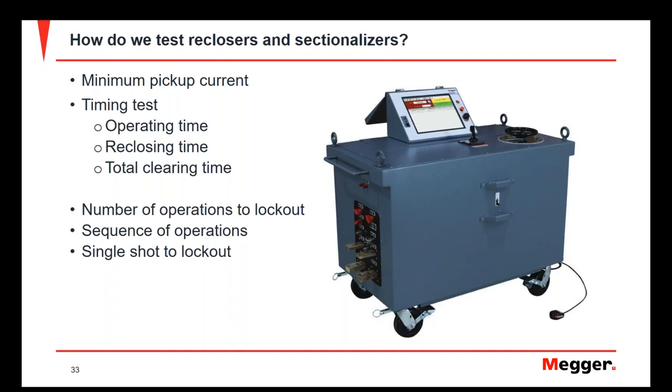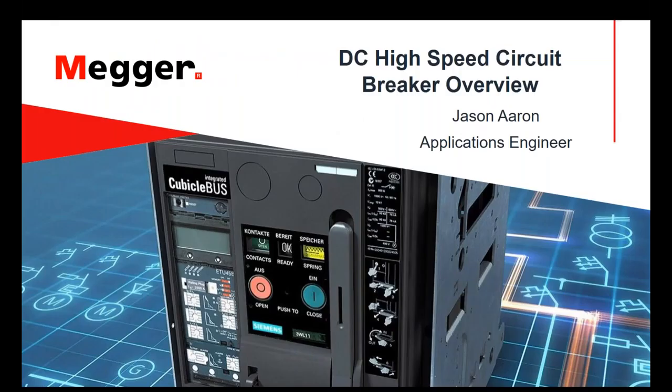And even though all of these processes can sound kind of complicated, the testing of these reclosers can be done safely and easily using a test set similar to the one we see here, which is an OCR, either the 15D model or the 50D model for higher current applications. And the test unit offers an automated user interface that helps make this testing more user-friendly for the technician.